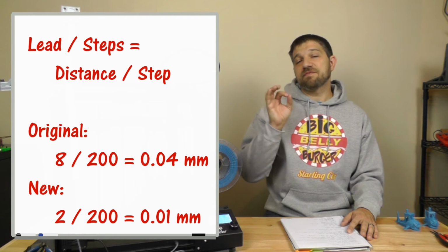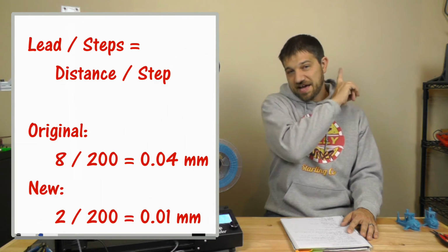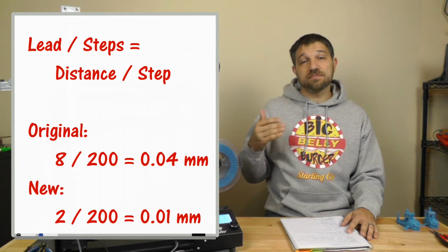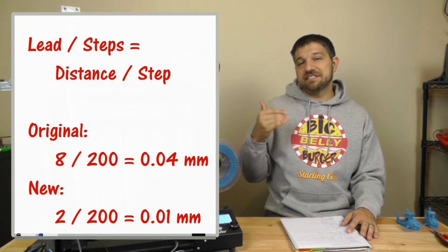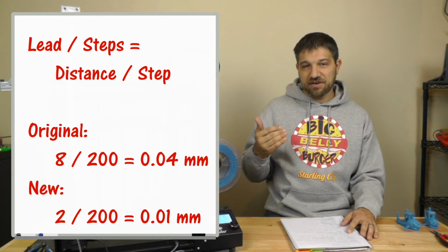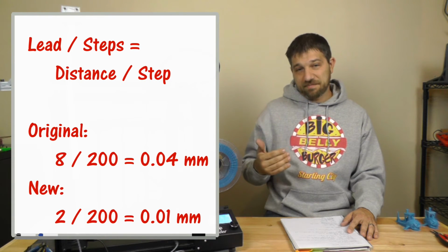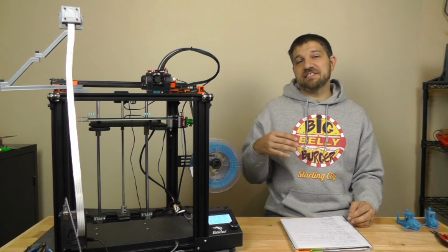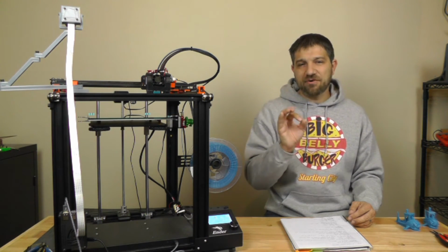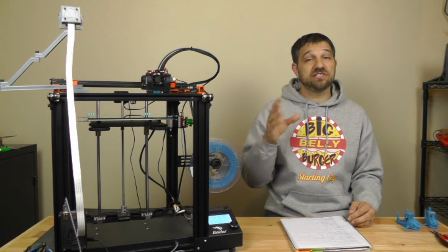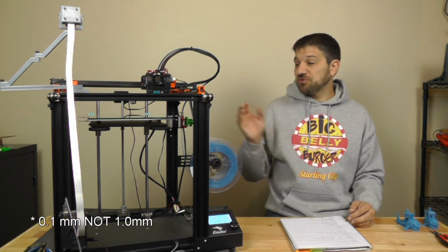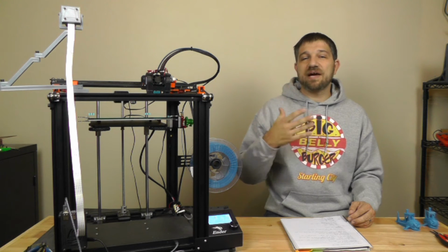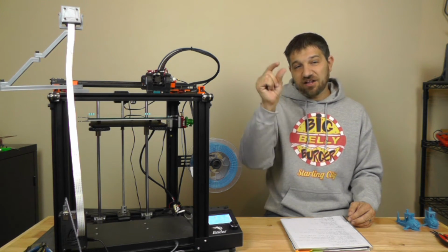What that means is, if you're familiar with what Chuck Hellebuyck refers to as magic numbers, our magic number has gone from 0.04 to 0.01. Now instead of stepping in those 0.04 millimeter increments, we can do 0.01 millimeter increments and have a much wider range of settings. Those odd steps, those micro-stepped ones which would have been in between, such as 1.0 millimeters, are actual physical steps of the motor that do not have to be micro-steps. Theoretically, this will result in better prints at all of those in-between numbers.